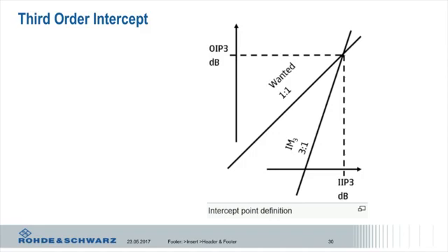So, when you, again, look at an amplifier, obviously I want to take a small signal and make it big, right? So I'm multiplying by some number or adding in dB to increase the amplitude of that signal. But the problem is that no device is perfect. So not only are you going to get that wanted signal, for example, if I had a 1 gigahertz signal and I want to get it from, say, minus 50 dBm to a higher number, I'm now going to increase that, but I'm also going to get some other things that are going to pop up, and you'll see that in a sec.